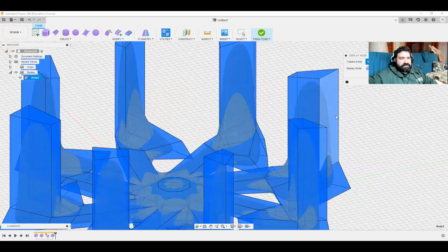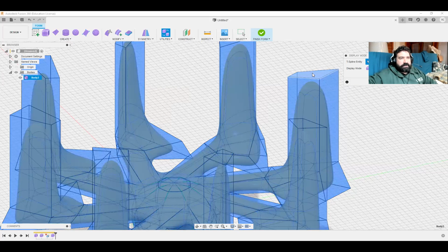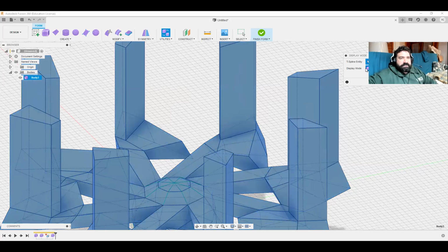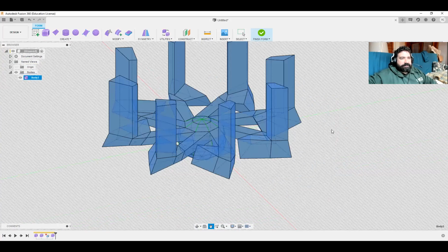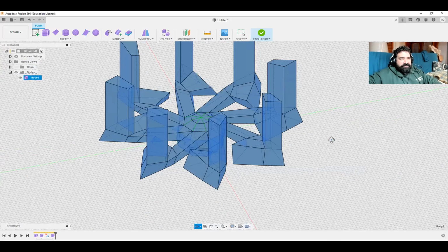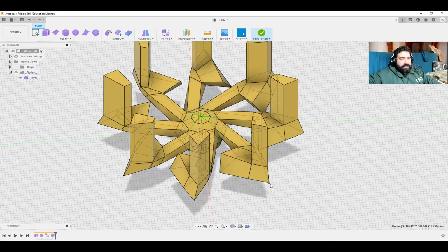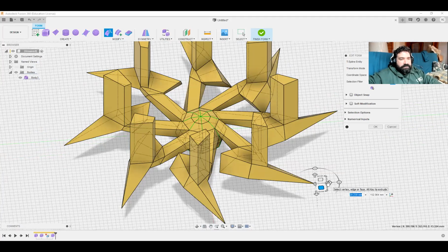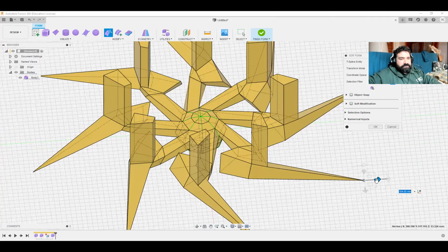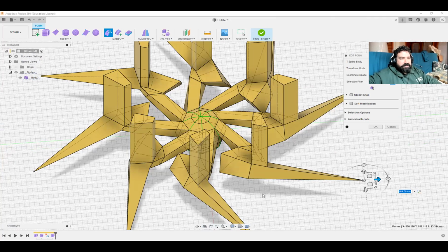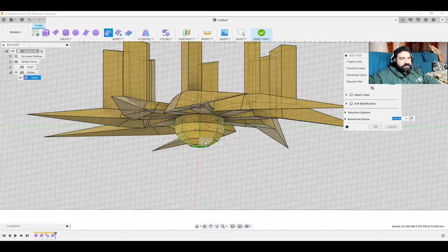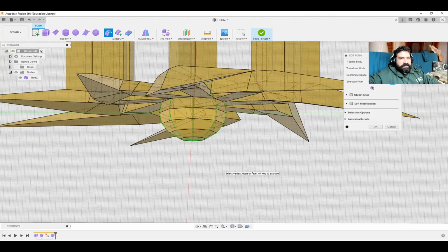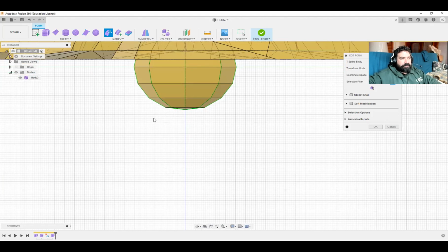See, now I just have a box face highlighted rather than trying to get the rounded face. So let me just go to box display, and I'll show you what I mean by that. All right, so now I can modify these a little more easily. So I can grab a point, go back to edit feature. Now I can drag these out a bit. Again, I can extrude faces, but you see how now if I make alterations to all of this, oops, now it won't be as difficult for the thing to compute, and I can see what I'm doing.